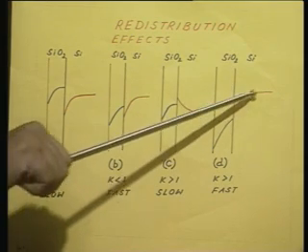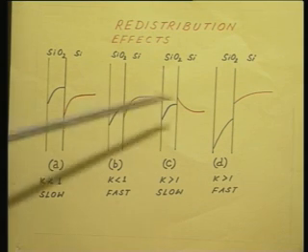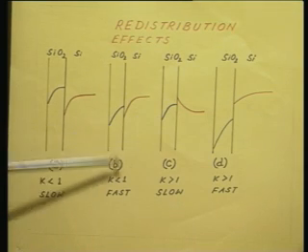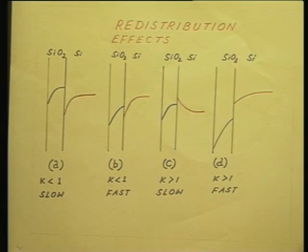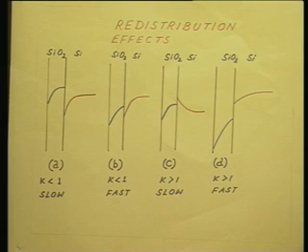And even this effect continues at the silicon-silicon dioxide interface. It just draws the gallium out from this region. So that if anything, the gallium concentration is a bit less at the silicon-silicon dioxide interface than inside the bulk. It does not get a chance to pile up, to build up. Okay.